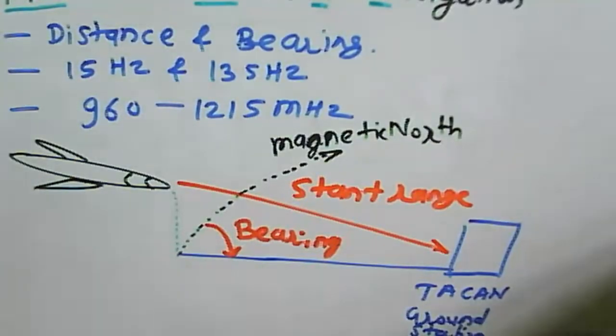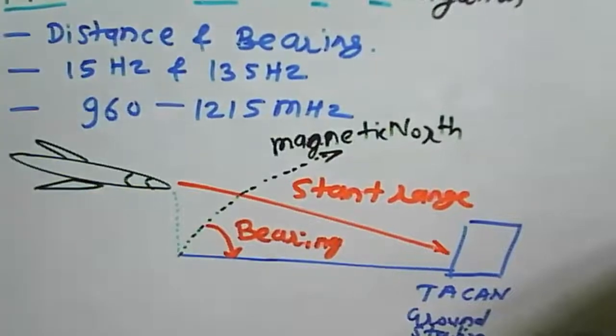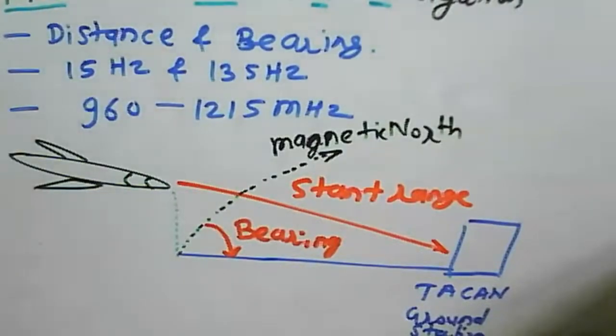In the same way your VOR transmitter sends the signal, similarly we have a TACAN system. That will be useful to find out the range there. So we can say that a TACAN operates to obtain the range information of the aircraft. And then how does it find out the range? We have seen earlier the DME system, or distance measuring equipment, in which the time required for the signal to travel and the delay are used. From this we can find out the range.